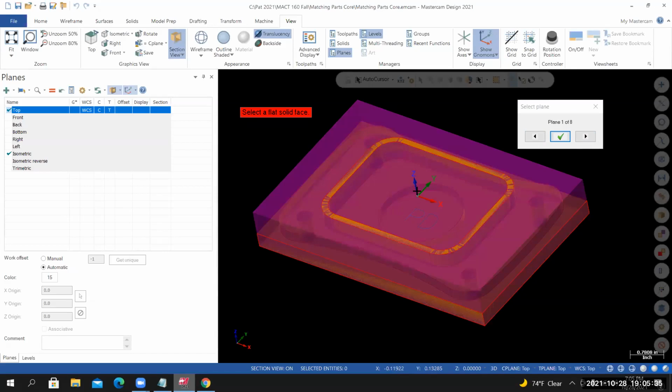It can be perpendicular from 2 directions. So that's why we have 8 options. Watch what happens as I scroll through this. We're pivoting about the Z. And then it flips over and then it pivots about Z again. So those are the options that we have as far as orientation is concerned using this method of creating a plane. In this particular case, I like this orientation.